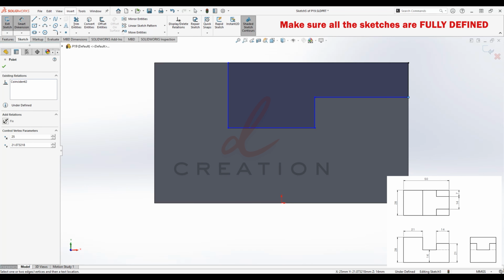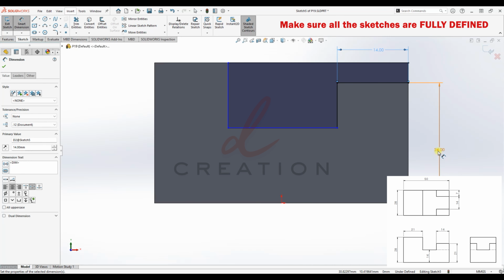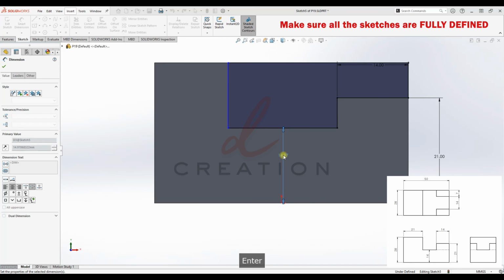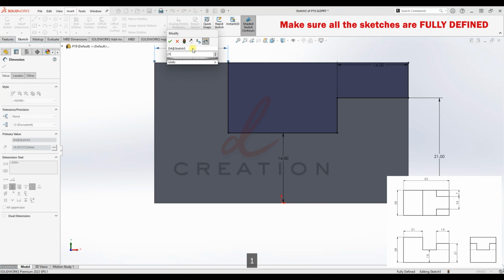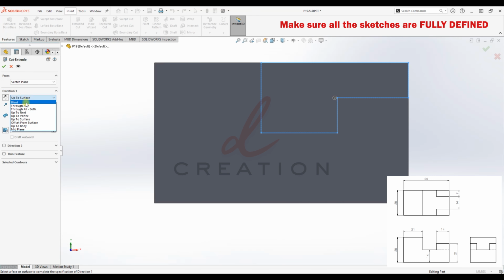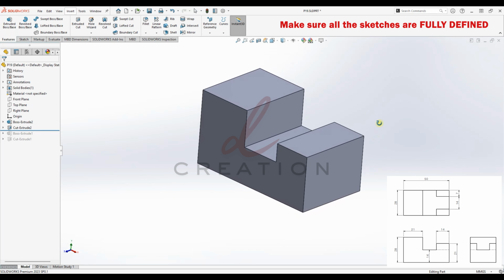We know that this distance is 21, and from here to here is 14. And this distance is also 21. Alright, so we have the area to cut. Exit sketch, cut extrude. You can select through all both, and okay. You see, now we can create the exact 3D part.